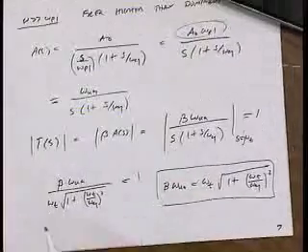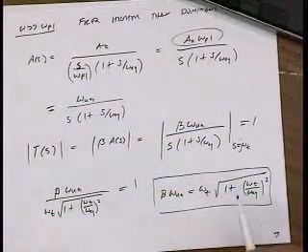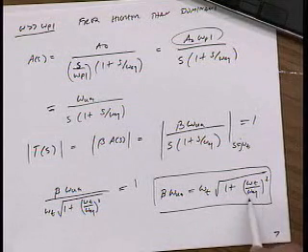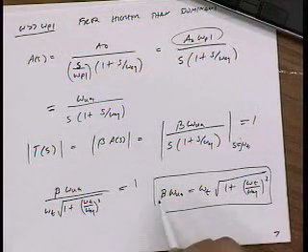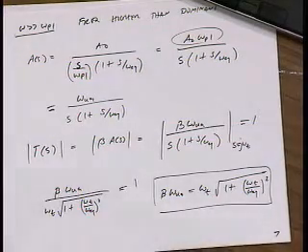Okay, I won't bother solving this equation. It's a simple quadratic. But you can see now that once you have the equivalent pole frequency, the open loop unity gain frequency, and beta, you can solve for omega t. Okay, and just as a check that I haven't made an error,